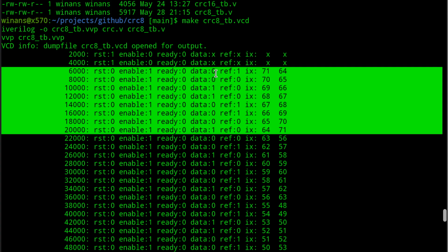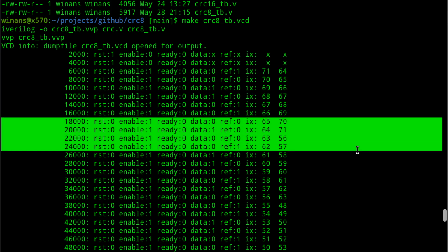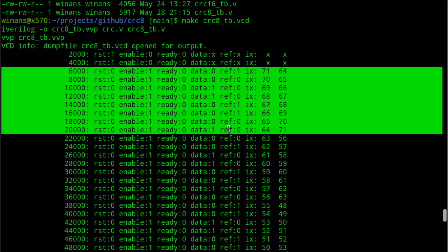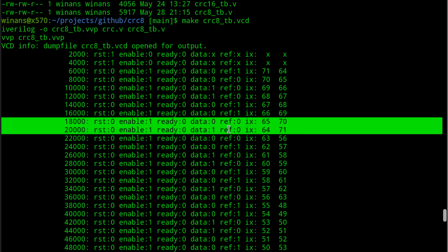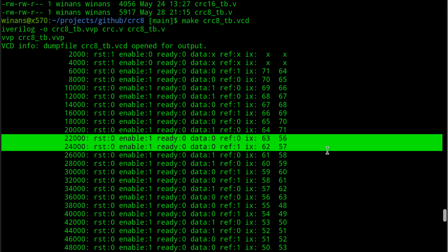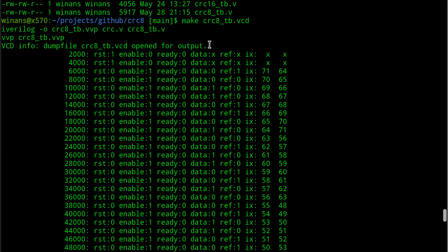Because when you corrupt a sequence of bits, you might corrupt these bits right here. But if you read in a byte and then reverse it, and then you process your bits, then these 2 bits will be far away in the CRC math from those, and you may not detect that error. You following me? If you're not, pause it and rework this out. You want to make sure that if you receive bits in this exact order, this is the order that they go into your CRC generator.